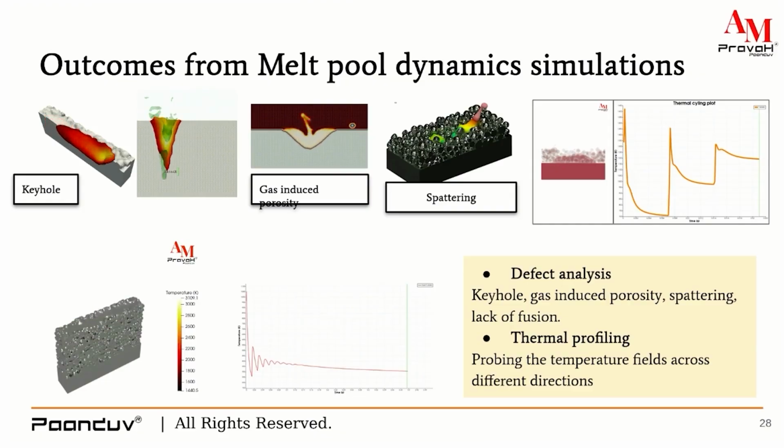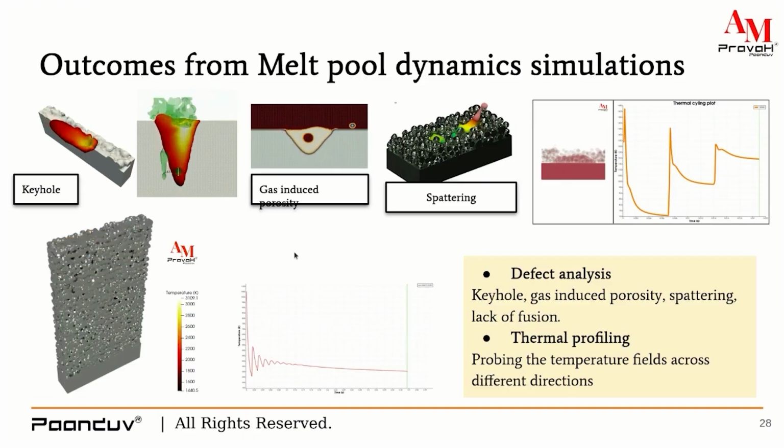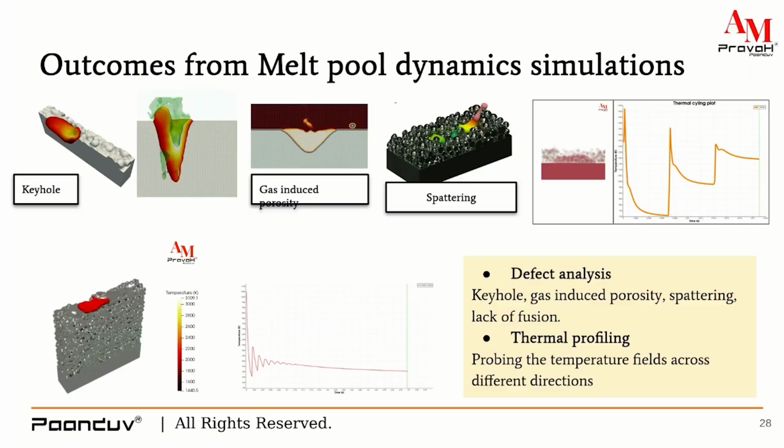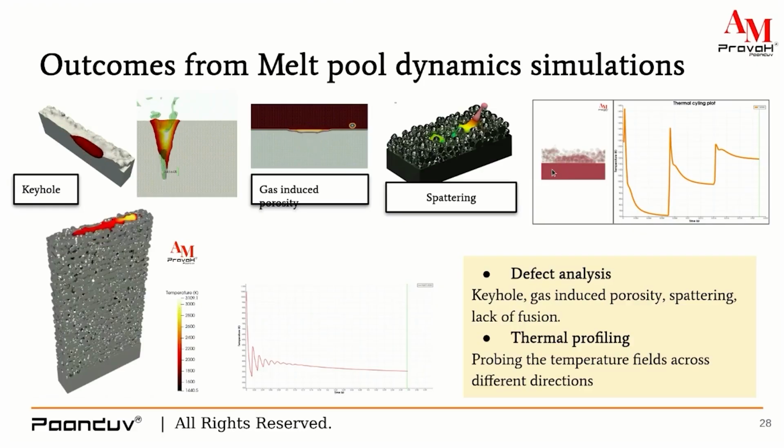As we do experimentally, we cut down the rough edges of your volume, and then you perform your experimental analysis for porosity. In a similar way, we cut a portion of volume in this part and we quantify what is the density in that part, and that way we calculate the porosity in the system. For this particular case, experimentally the porosity is reported to be 0.55%, and porosity by simulations we achieved 0.63%.